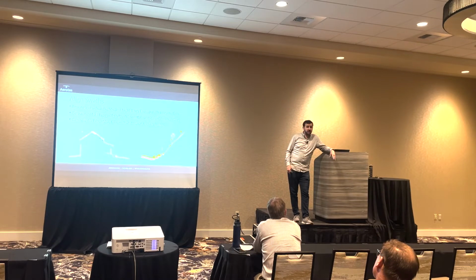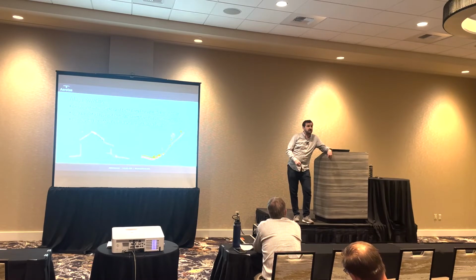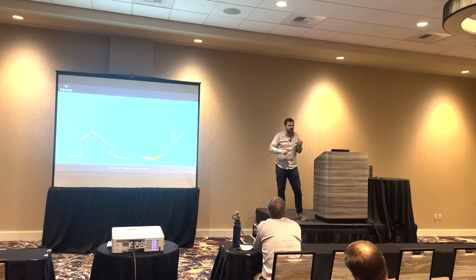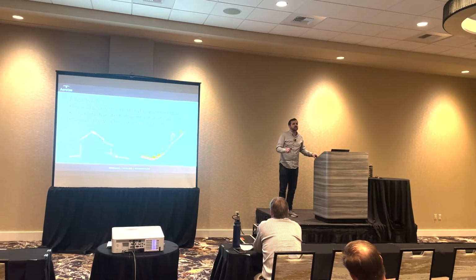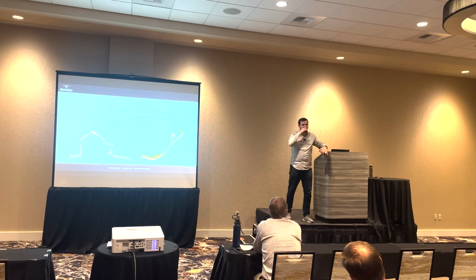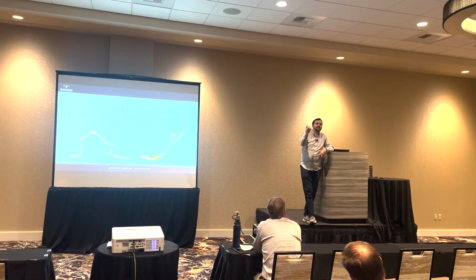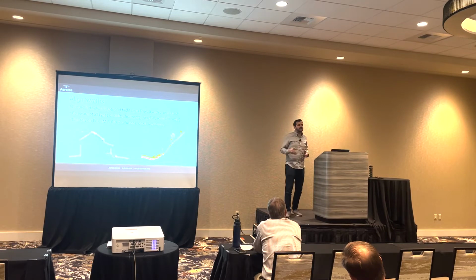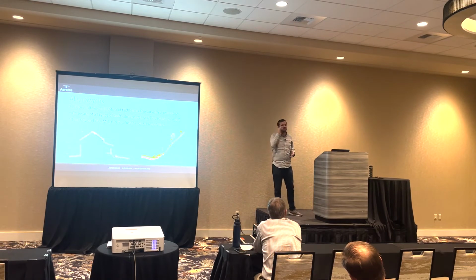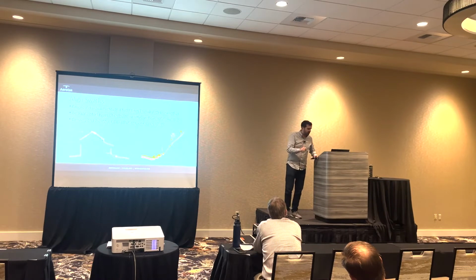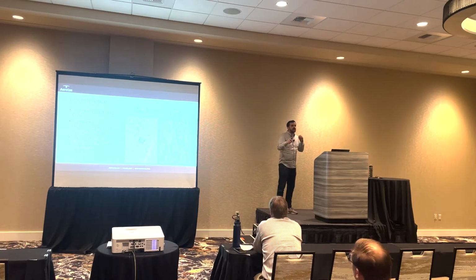So generally speaking, RTK data, the real-time kinematic data, is going to be extraordinarily precise. Precise meaning your relative accuracy, one point measured next to the other. But it's not going to be extremely accurate relative to measuring one point, coming back a month later measuring the same point. It might be off by a little bit. PPK data is what gets you that final accuracy, bringing it down to global level accuracy. But RTK data is typically going to be very, very precise, which is one of the most important things, because our next step is georeferencing.